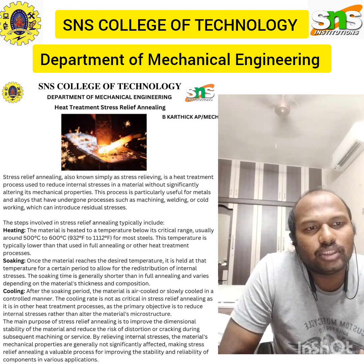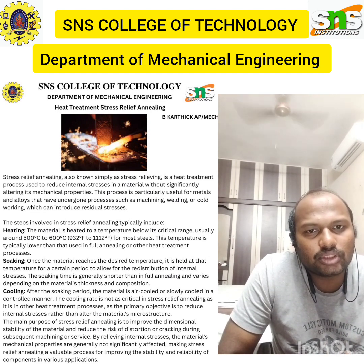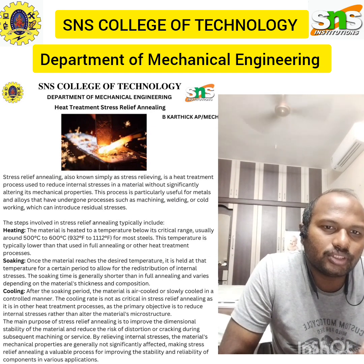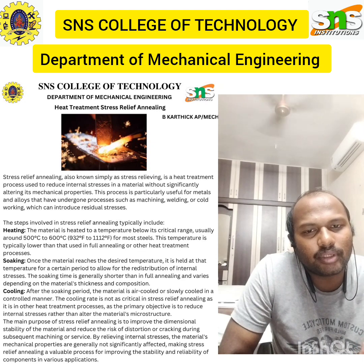The second one is soaking. Once the material reaches the desired temperature, it is held at that temperature for a period of time. The soaking period allows the material to relax. That means the soaking period allows the internal stress to gradually redistribute and relax, leading to a more uniform stress distribution within the material.